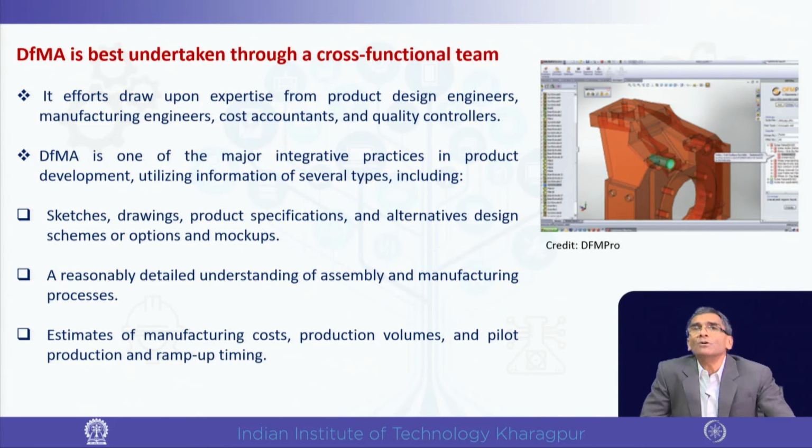Production volume is very important, because it depends. If one has to produce one component, then naturally the process may be something else. For example, if one needs 10 pieces, one may go for machining, but when millions of pieces are to be produced, then people might go for casting, otherwise machining would mean wastage of material and time both.